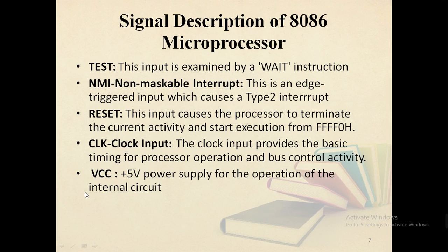Next, coming to TEST bar, this is an input examined by the WAIT instruction. If the TEST input goes low, execution will continue, else the processor remains in an idle state. Coming to NMI, non-maskable interrupt. This is an edge triggered input which causes a type 2 interrupt. The NMI is not maskable internally by any software.